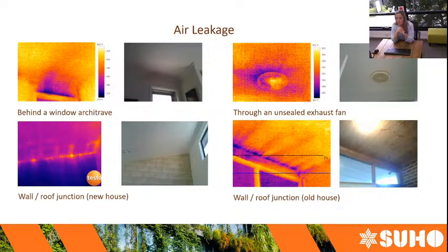A lot of them, especially in bathrooms, don't have these dampers because they're not required by the building code, especially in old houses. So they're not usually installed. But exhaust fan dampers, even though they're in unconditioned areas, have a fairly big impact on thermal comfort throughout the entire home because they're allowing a lot of air to move in and out continuously.